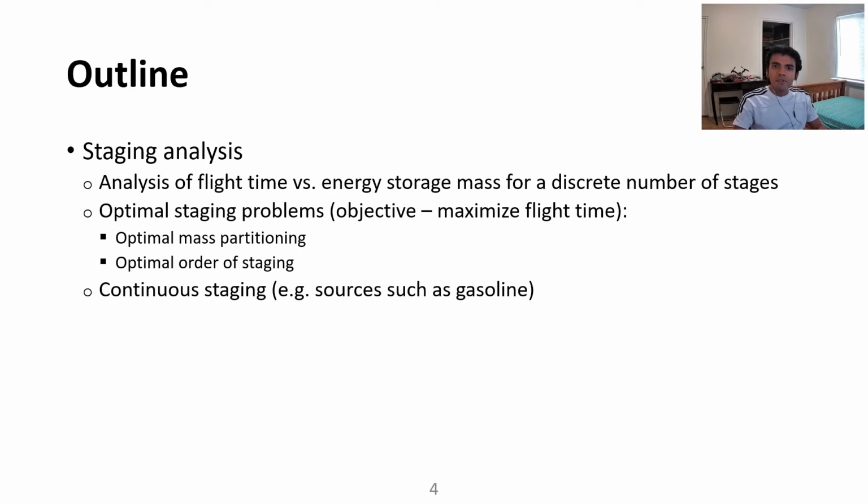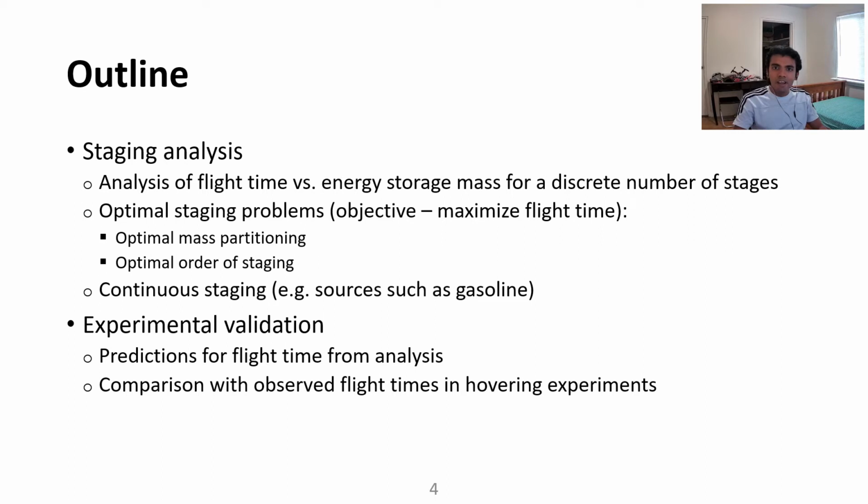We will start by going through the power consumption model of a multirotor and derive the flight time with respect to the energy storage mass for various number of stages. We will then cover two optimal staging problems with the objective being maximization of flight time. Then, we will cover a limiting case of staging, namely continuous staging. Secondly, we will show experimental validation of the staging analysis on a custom designed two-stage quadcopter. Lastly, we will go through the environmental concerns of staging and the special cases in which staging can be utilized.